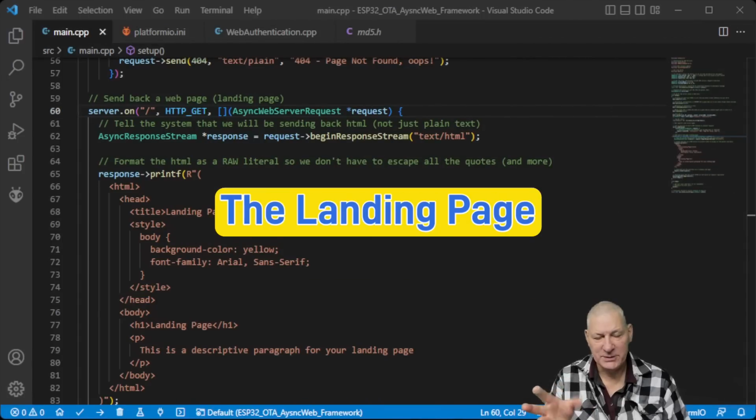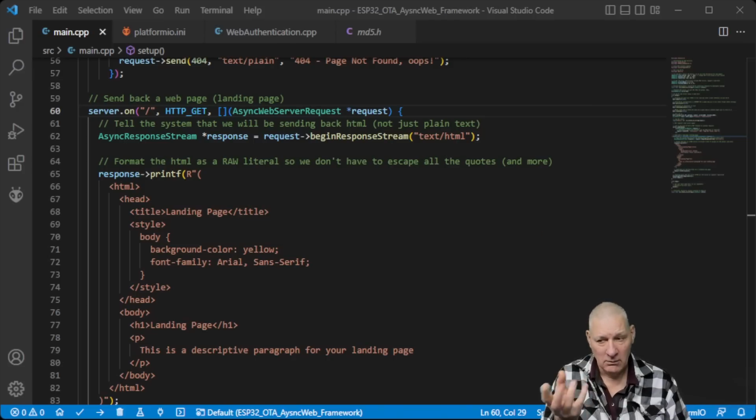So cool, your ESP32 device is now connected to your network, but it's pretty dumb, nothing's happening. We're not talking to it and it's not talking out. It's just connected. But by typing in its IP address, in this case 192.168.1.103, it means that yes, your request will be routed by your router in your Wi-Fi environment down to that device, and the device will say, oh, what page do you want? Well, you've not actually given it a page, you've just given it the address of the device.